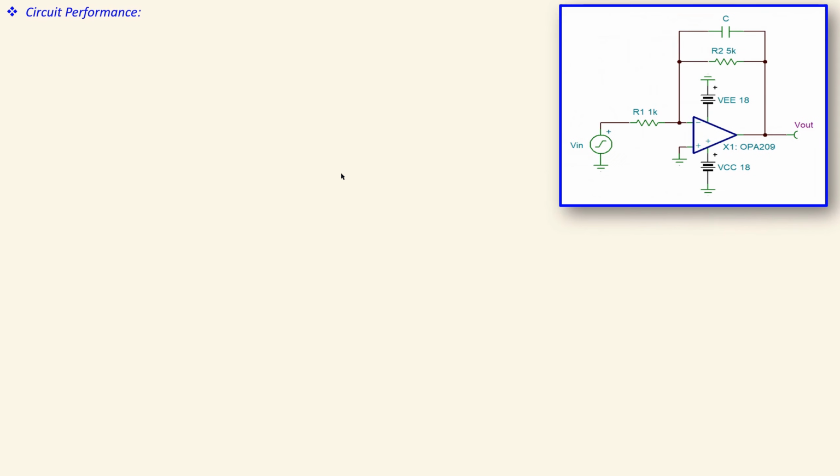So let's look at the circuit performance now in more detail, because that will of course determine our noise performance of the circuit also. Let's first determine the gains. I purposely used "gains" instead of "gain" because you have the signal gain and also the noise gain. The signal gain is used to determine the signal at the output, so that is the gain used to amplify the output. And you have the noise gain, which is the part that amplifies the noise at the input and the